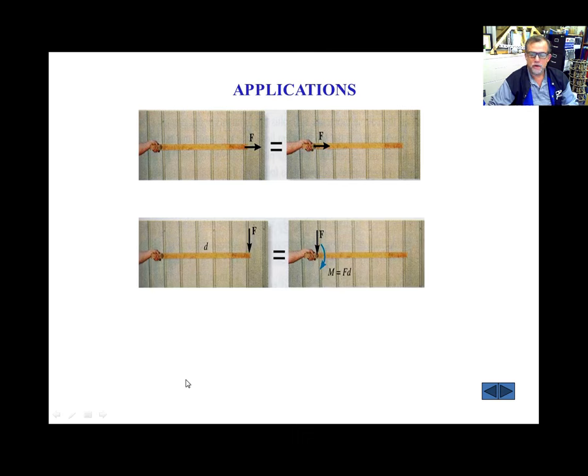And this is what we're going to be trying to do today. In this case, for example, you don't have the same situation, because in this case that force is acting through the point, and the only thing that I can do is slide that force here, but this system and this system are equivalent because of the transmissibility principle. Remember that there's no moment, there's no distance involved. However, this force is the same one that I explained to you before.